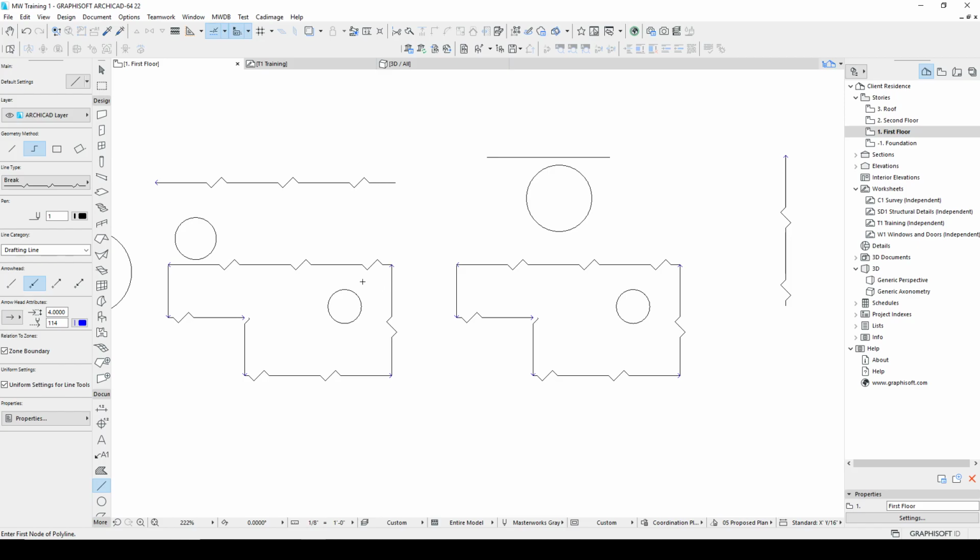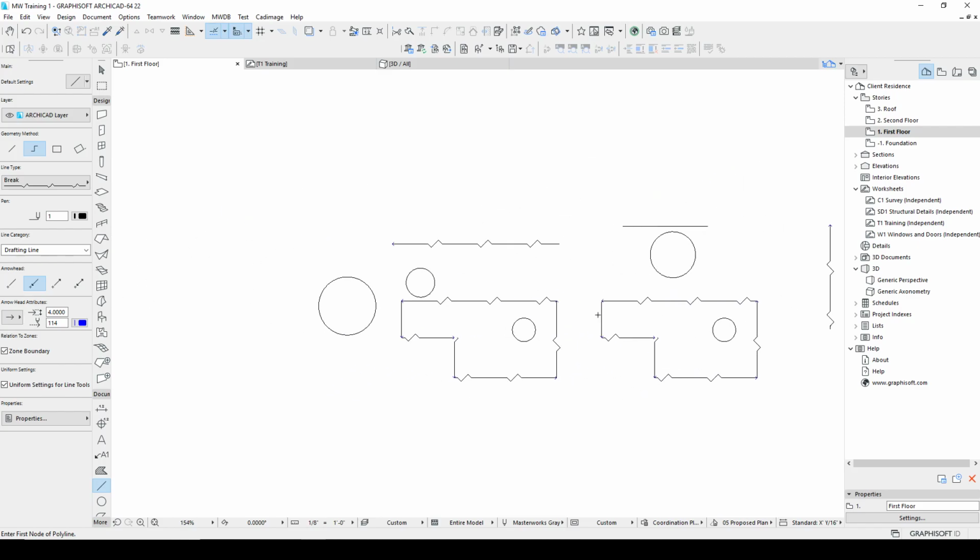The last thing I'm going to show you with this is something that allows you to change properties across different elements. Let me give you an example of that. So for example, if I want to change this circle and this line to a solid line, I can't change both at the same time because only one command is available, and I can't do both unless I come up here and I hit this Edit Selection Set.